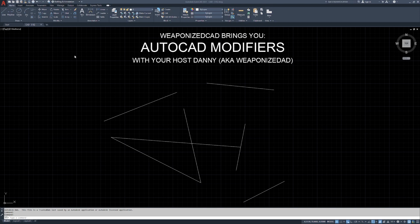So your modify commands are up here in your ribbon in your home tab in the modify panel. First modifier is move, and move works similar to grabbing the middle grip of an object. This is technically moving this line, even though down in the command line it's telling us that it's stretching it. Essentially it's stretching the entire object, which is a pseudo move command of sorts. So let's click the move command.